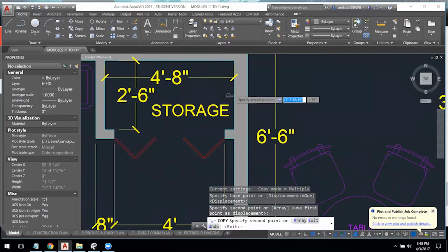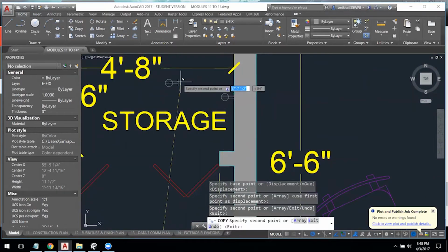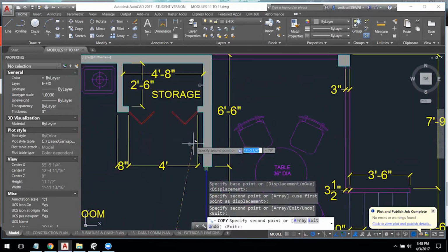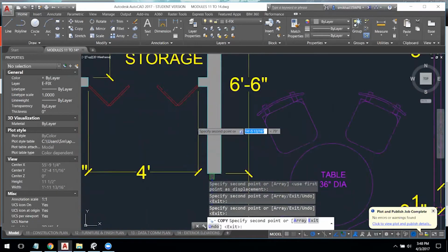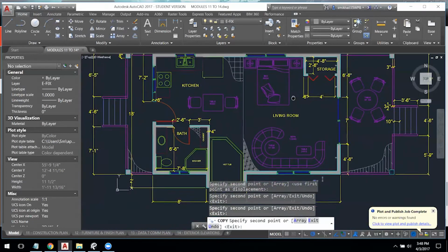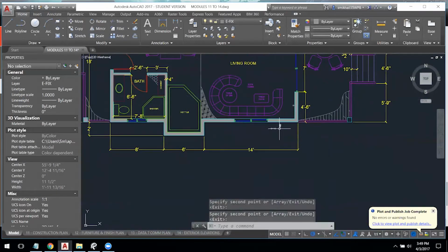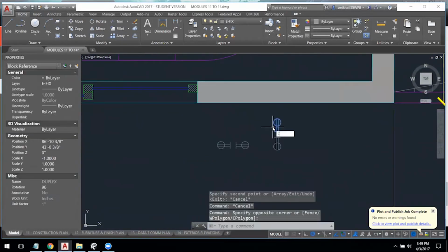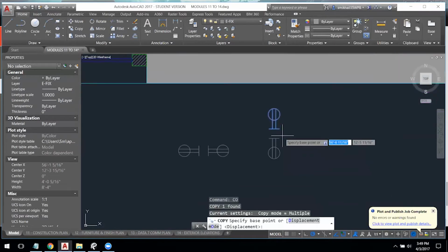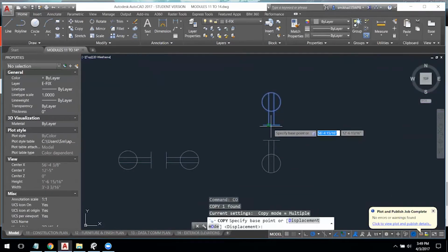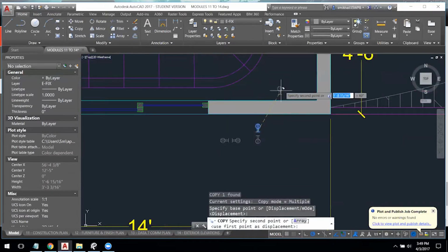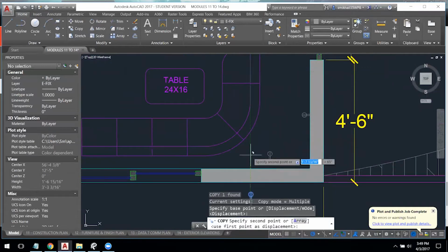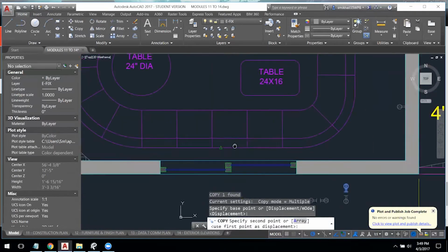You may want one outlet in the storage in case you want to put something and plug it in here. And you want to keep one available out here. And basically, there's an electrical code that tells you that you cannot go, I believe, 12 linear feet along a wall without having an outlet.